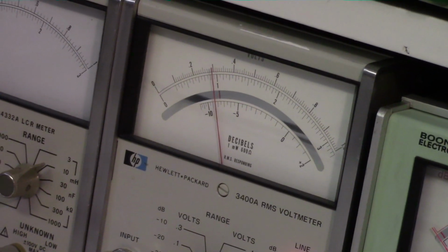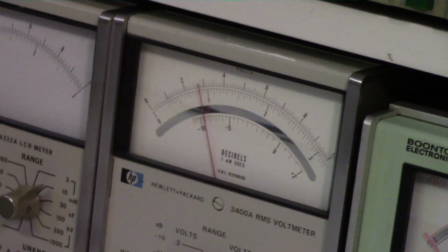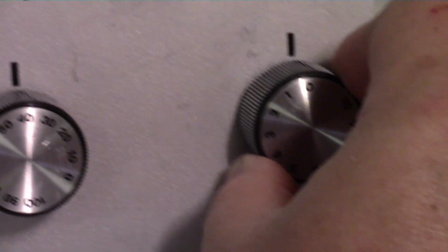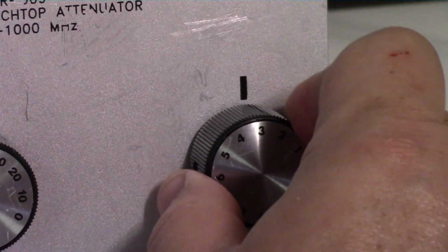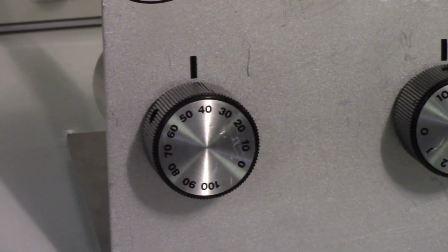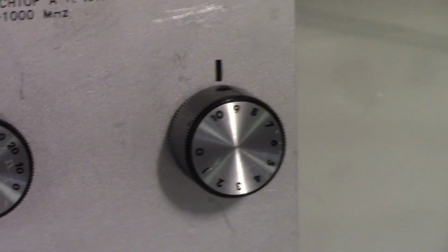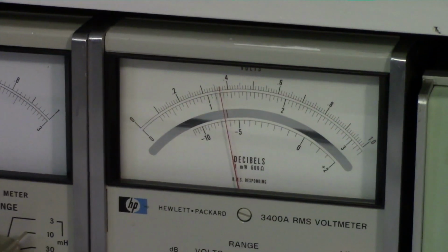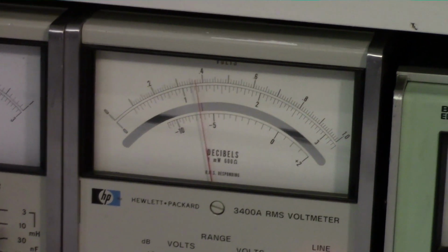We want it to drop 3 dB, but we're dropping about 8 or 9 dB. So that means our signal is, again, too strong. So what I'm going to do now is start dialing in 1 dB increments. And let's put in about 9 dB here. Let's leave that set to 40 and 9, so we've got 49 dB. Again, the meter level has dropped because we're putting in a much lower level RF signal.